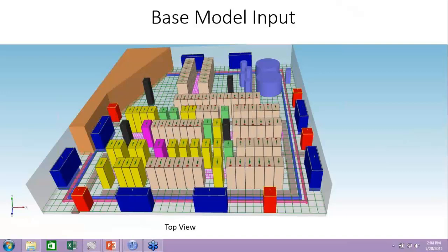And there's already been a question that's come in, Lauren, about the size of this data center. He's asking about slab to slab. Slab to slab, this one does have a ceiling plenum in it. It's not turned on at the moment, so there is a ceiling above, and we're going to expose that later. The room itself is 10 feet, and this subfloor is 1.5 at the moment. So slab to slab would be 13.5.